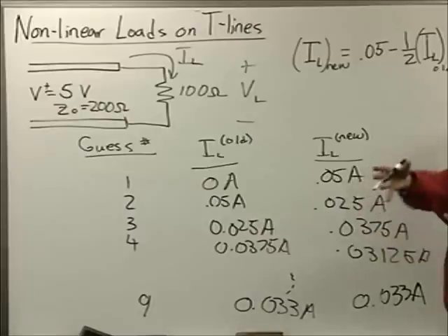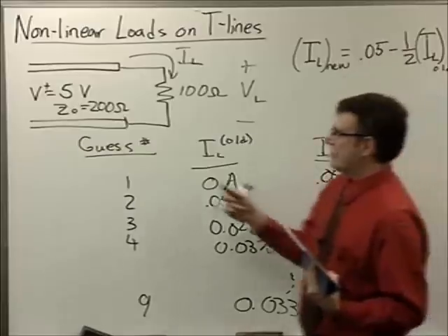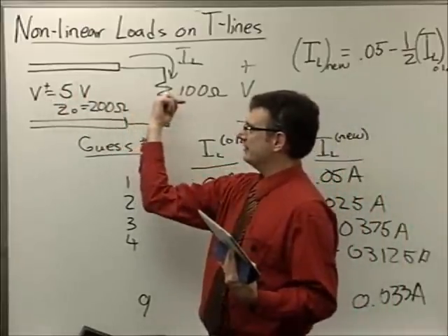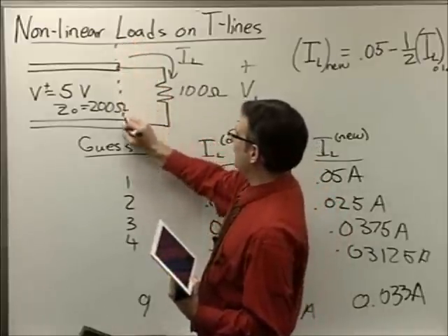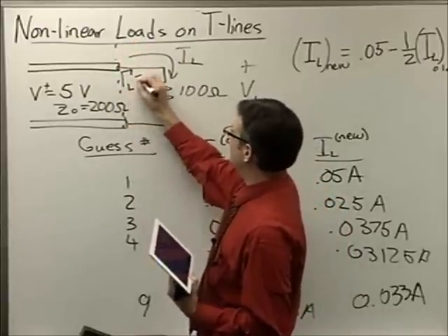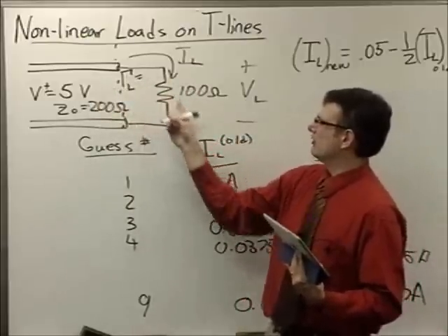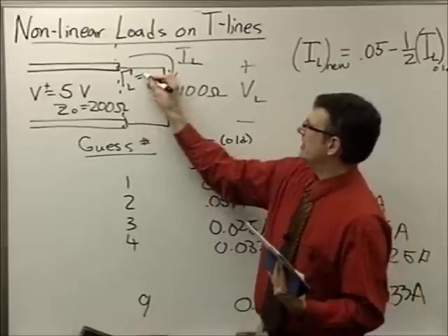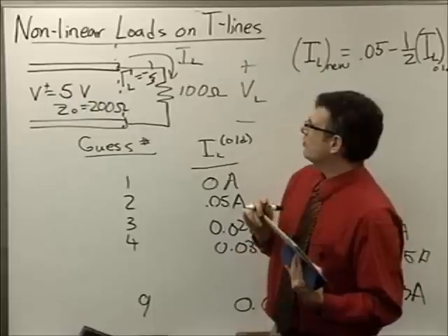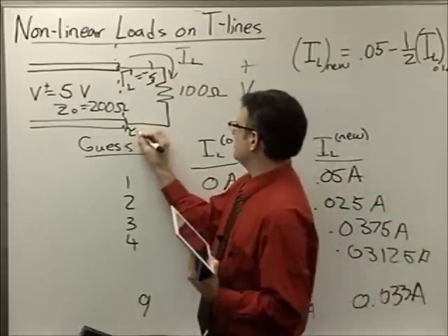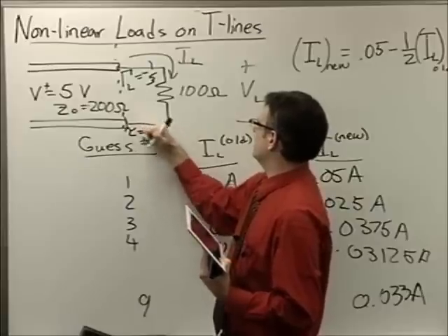So, okay, let's take advantage of this. Now let's do what you said. If I plug this into one another, then I know that I've got V plus going down. Let's use some transmission line theory. I've got a load reflection coefficient, gamma sub L, of 100 minus 200 over 100 plus 200. That's negative 1/3, right? Negative 1/3. So my transmission coefficient is actually going to be 2/3.